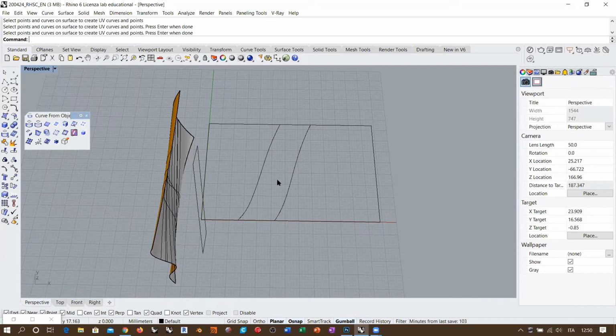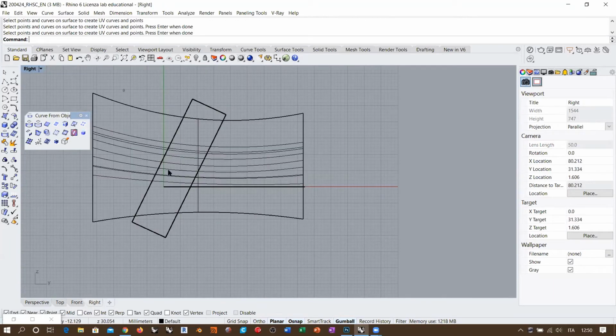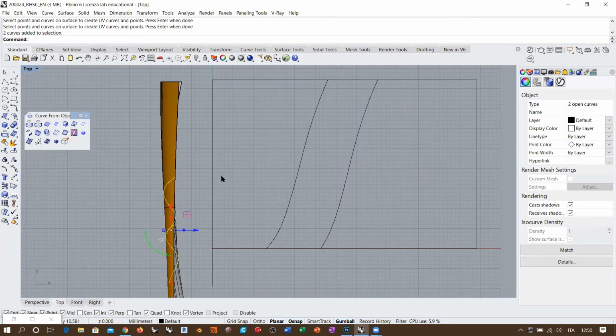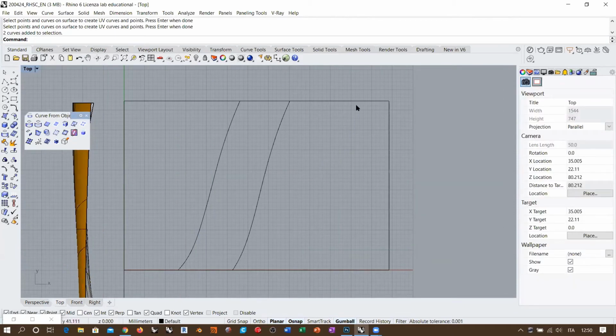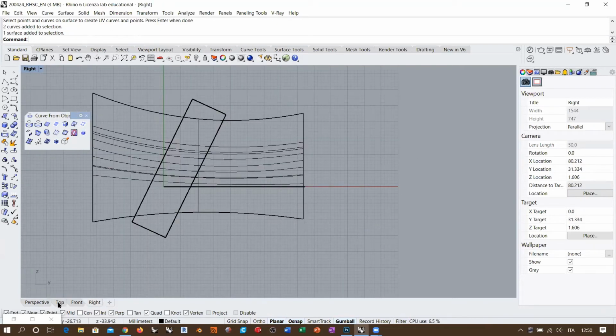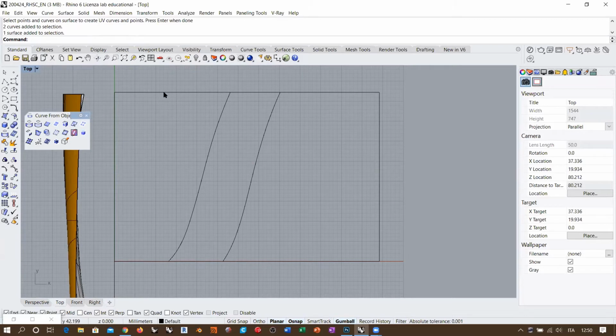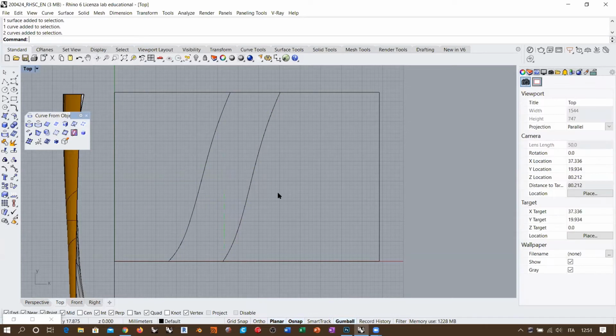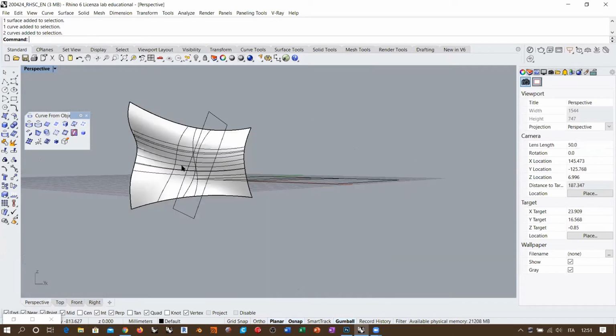Now you see that even if, from the right viewport, those two lines are basically straight and parallel because they come from a projection, when you work with the parametric representation inside the parametric domain, it becomes rectangular and the lines become wavy. So geometrically, we have a wavy surface and we have parallel lines. But topologically or parametrically, we have a rectangular surface representation and wavy lines. So our text must become wavy in order to be applied properly inside this area.